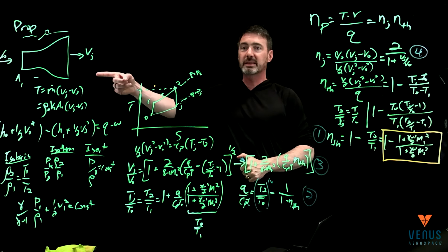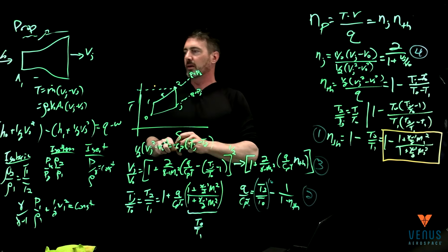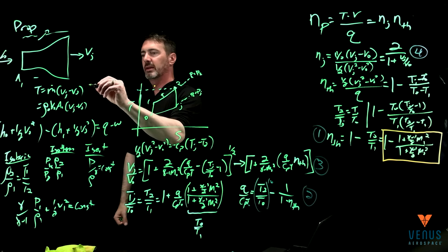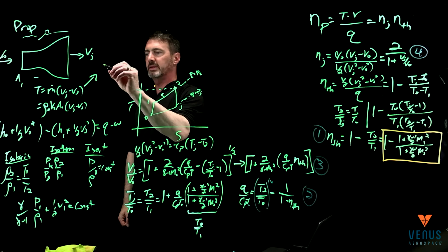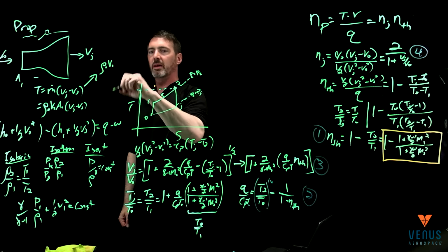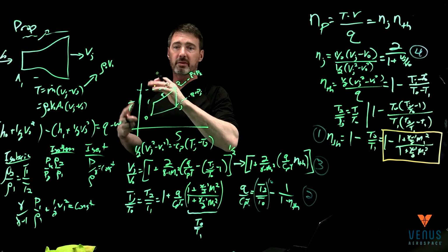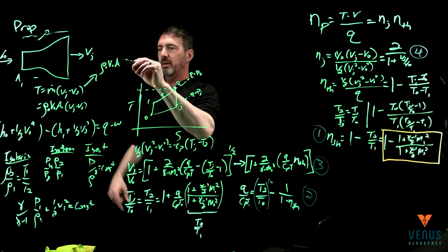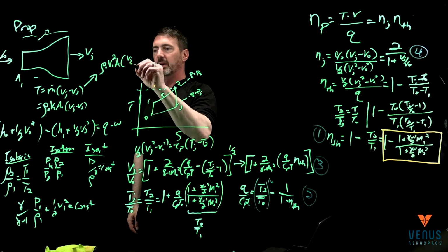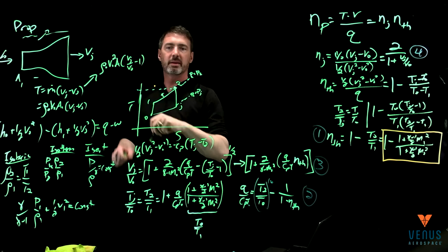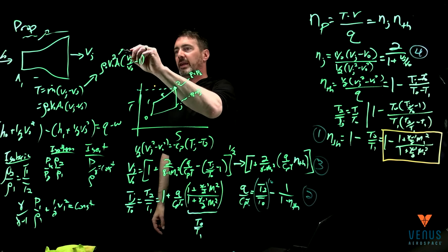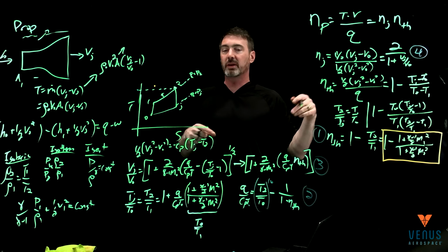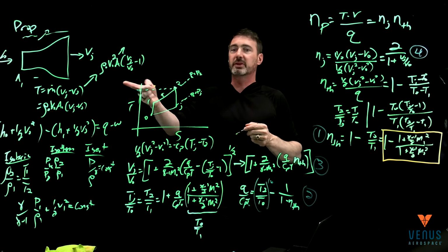And then, if we need to size the system, I'll come over here and just say that thrust is equal to rho naught V naught. Those are conditions: I want to fly at this altitude and speed, times the area. And then if I pull out another V naught, that's actually squared, and then that's Vj over V0 minus 1. I input that in there. So now I can solve for A. If I need an engine that, when I'm adding this much fuel, makes this much thrust, I've got it. I'm done. I've now sized my engine.